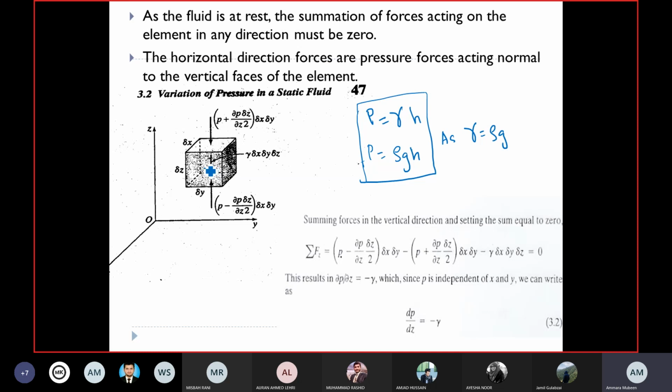Okay, so for this you have to check the rate of change of pressure towards the top surface and the rate of change of pressure towards the bottom surface, isn't it? So you would have to use that Taylor series expansion for that. If you know the pressure gradient, you would be able to get the pressure on the surface. Since you have said that you are assuming the pressure at the mid is P, or you can say the average pressure on this cubical element is P.